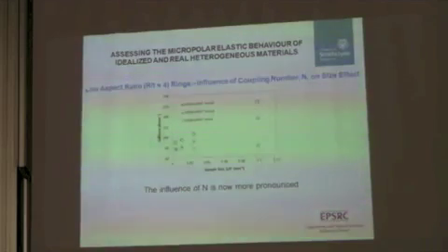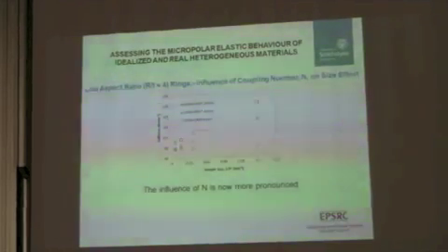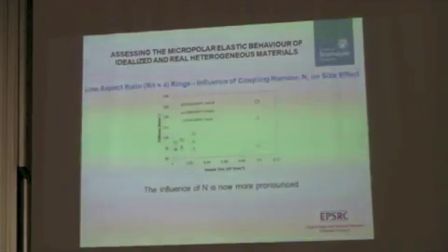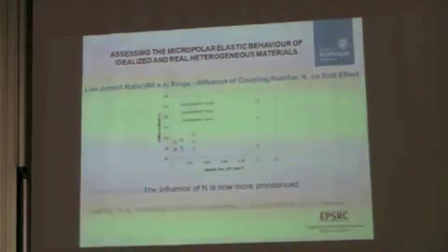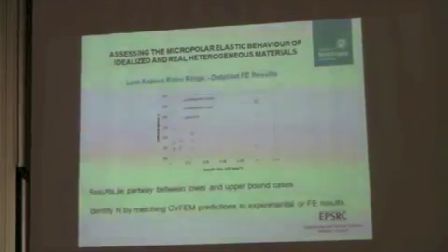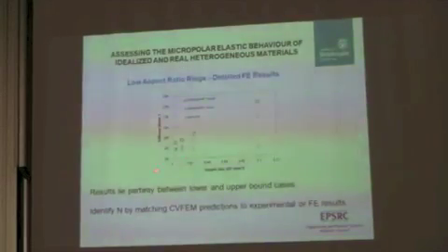So we do tests on these less slender ring samples, where we've reduced the aspect ratio to this value of 4. And in our experimental data, the stiffness variation we measure with size is given by the crosses there.